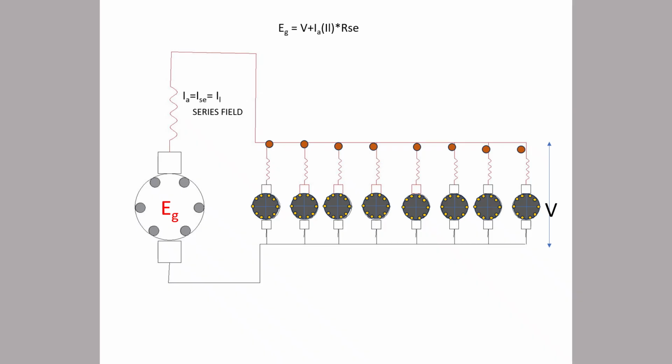In an electric locomotive, we use a DC series motor, as it has good starting torque. But nowadays we have replaced it with a three-phase induction motor with IGBT and GTO, insulated gate bipolar transistor and gate turn-off. The electronic system has come, and the control is through variable voltage, variable frequency. This is the modern technology now in use.